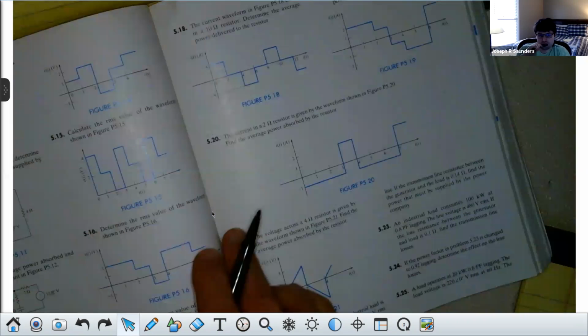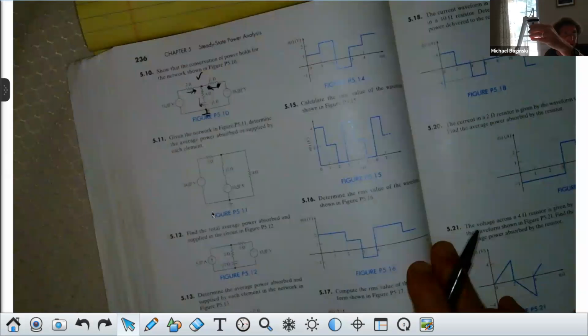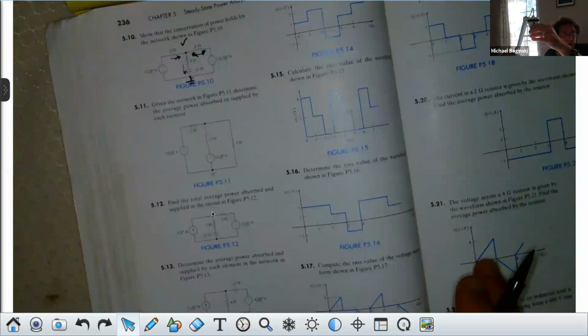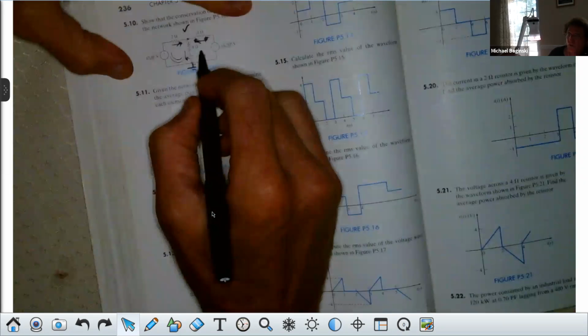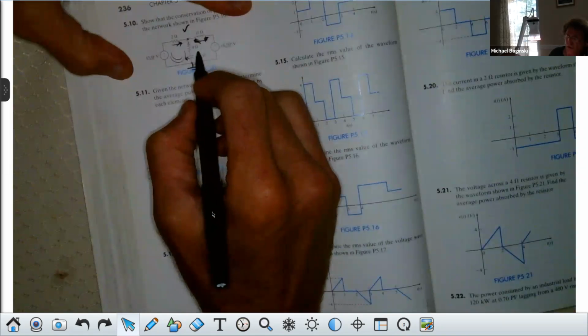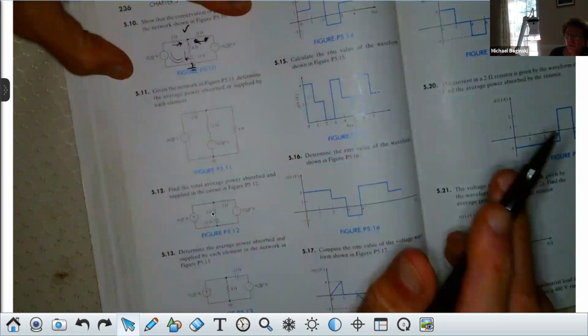Let me do what you're saying. And you're absolutely right. You could easily do it that way, but you're going to get a 2x2 then, right? Now you're going to get a loop here and a loop here. So you have I1, I2, so you have matrix math, right? You have a 2x2, don't you, class? Otherwise, I just had one equation with one unknown. That's the only reason I chose nodal.